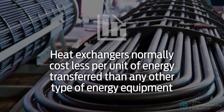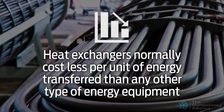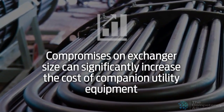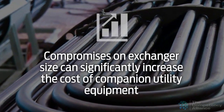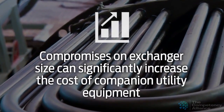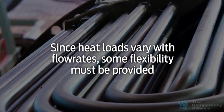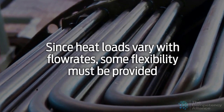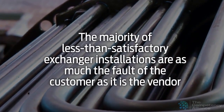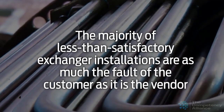Heat exchangers normally cost less per unit of energy transferred than any other type of energy equipment. Compromises on exchanger size can significantly increase the cost of companion utility equipment, such as propane refrigeration or hot oil heating utilities. Since heat loads vary with flow rates, some flexibility must be provided. The majority of less than satisfactory exchanger installations are as much the fault of the customer as it is the vendor.